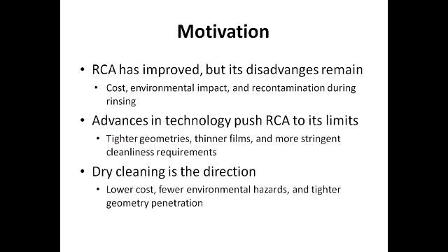Meanwhile, advances in technology push RCA to its limits, like tighter geometries, thinner films, and more stringent cleanness requirements. So dry cleaning is the direction. It has lower cost, fewer environmental hazards, and tighter geometry penetration.